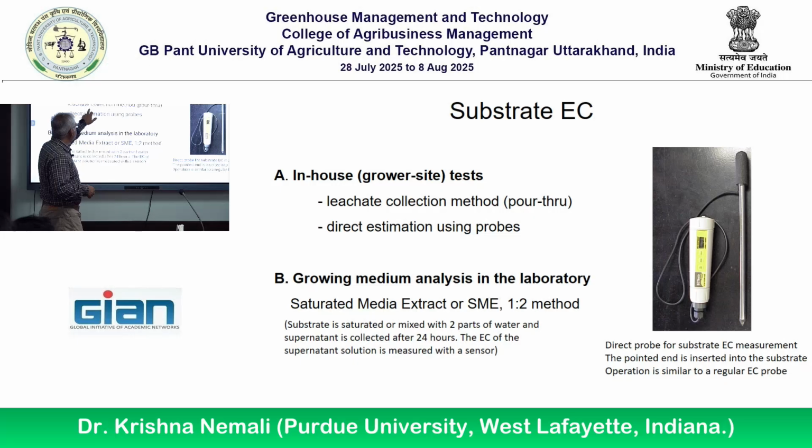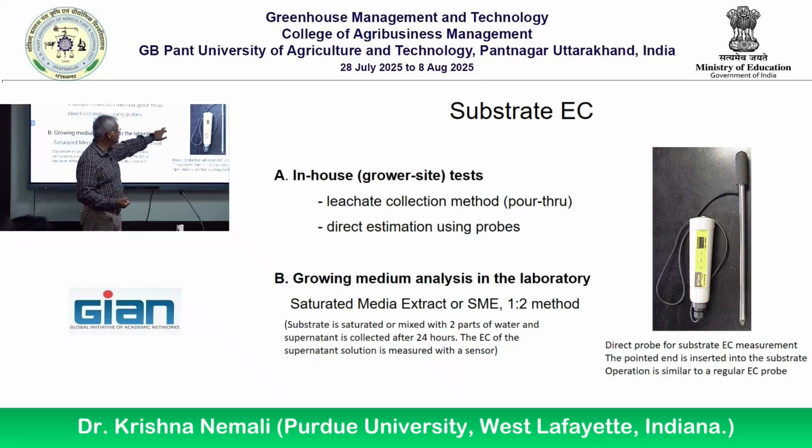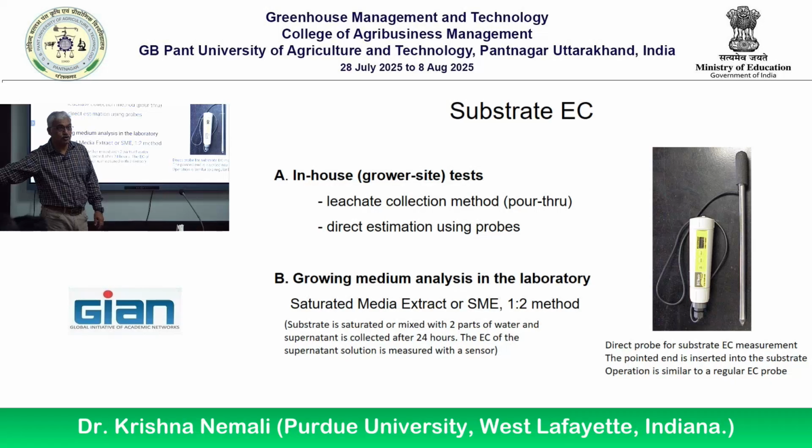You can use the leachate collection method, also called the pour-through method, which we will do this afternoon, hopefully, if you can give us some parts. That is pore water EC measurement. Or you can use direct estimation probes like this to measure bulk EC. Both are related to substrates, not to the fertilizer solution you're supplying.